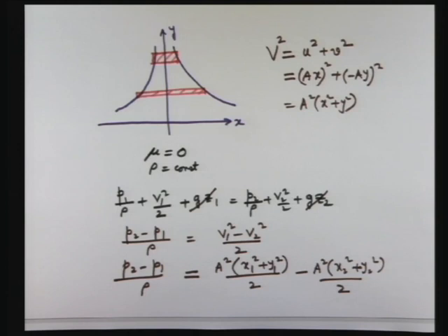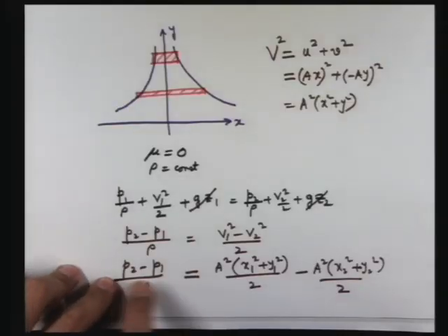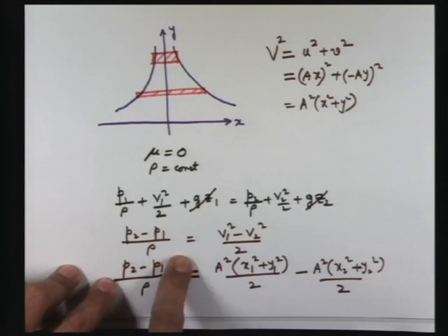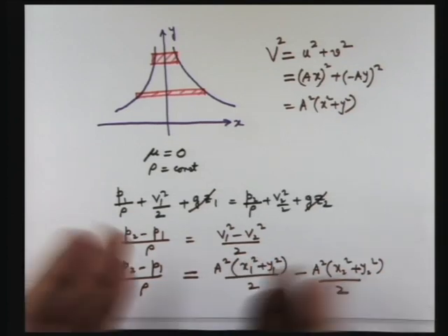You find out del P del x and del P del y and find out the pressure difference dP as del P del x into dx plus del P del y into dy. And then you check by integrating that the pressure difference that you get from the differential form of the Euler's equation is same as this final answer. That is a long way of solving the problem. This is a short way of solving the problem. Of course, you have to be assured that the flow is irrotational.